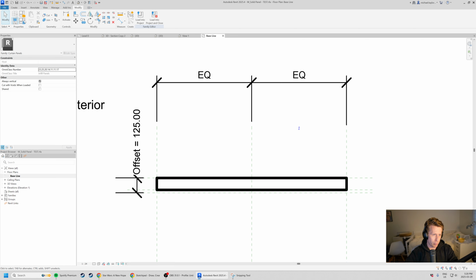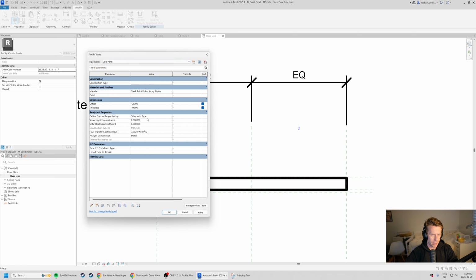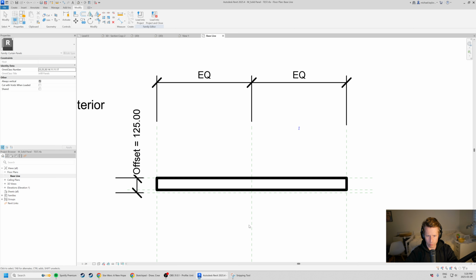Do we remember how to get rid of thickness? It is a parameter. So we're going to jump up to the family parameters up here. And I'm actually going to delete the thickness because I don't want that thickness. It's a more complicated geometry. So I'm going to right click. How did I delete this last time? Oh, down here. So I'm going to come down here and delete the parameter, hit OK. I thought it was going to give me a warning. Looks like it doesn't care. Cool. Delete this little piece here.